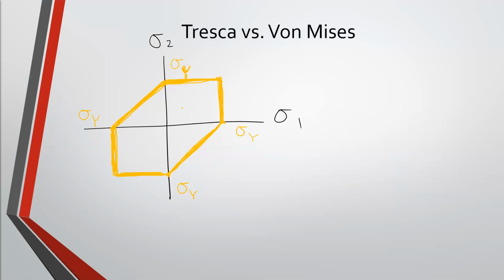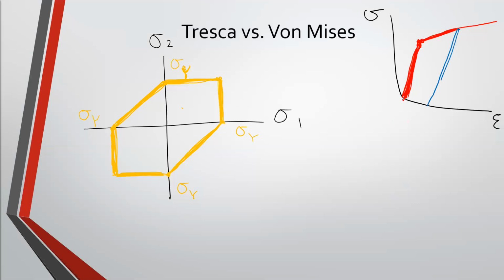And so you can go back to thinking about stress and strain. So remember we talked about, say, our stress strain curve. If we're in the elastic region, we move up and down, right? This is our loading, unloading. But then when we come out over here, we yield at this point, and now we move over here. Now if I unload like this, parallel to that initial curve, and then reload, I go up this curve.